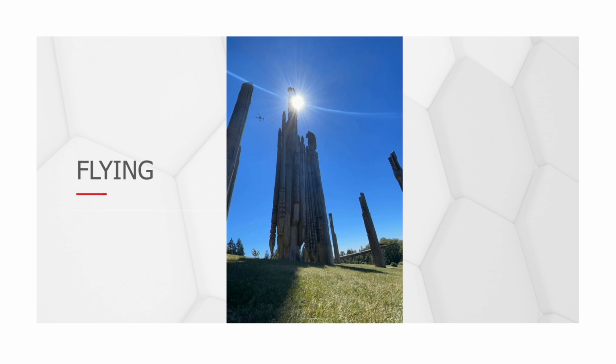So we have the drone flying, we also have Victor capturing the ground shots, but you can see how quickly the shadow is moving on the ground. So time is at play here, especially in the later afternoons. You're going to have some drastic moving shadows, especially when you do a multi-dimensional building with very complex structures. Right. While we're capturing these photos, it's important that we try to keep our ISO as low as possible to avoid noise, and also adjust the shutter speed as we go.